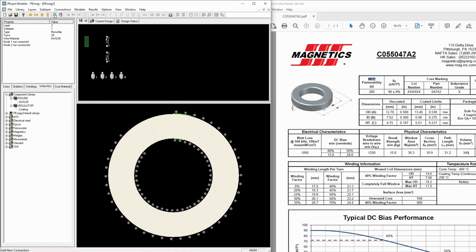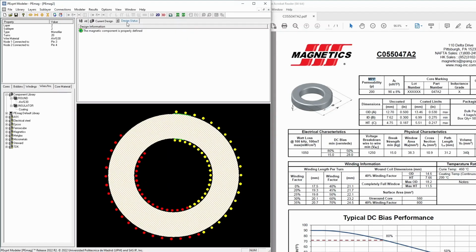So this is the connection here, and we're just going to connect the first one to the top, second one to the bottom, and you do have to be careful of the polarity here. We can check it in 3D model, but we'll just do the first one to the top, second one to the bottom, and if we follow it all the way through, it should work, because this one has a different polarity than this one. Right click to get rid of that tool.